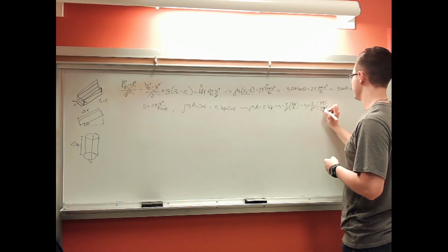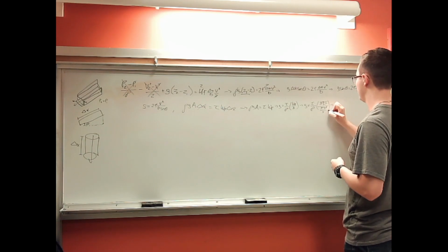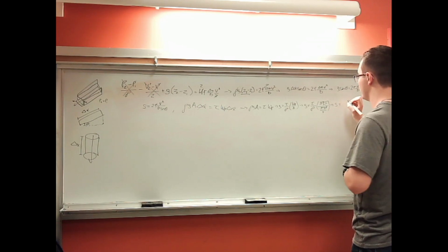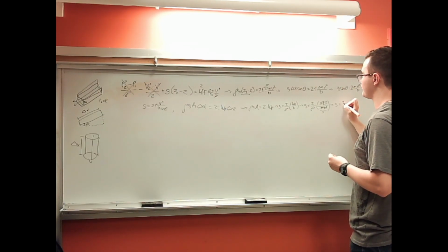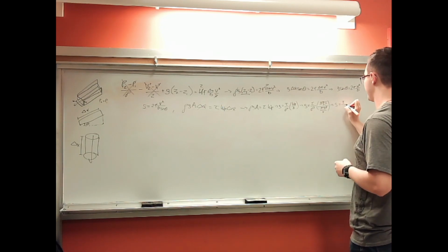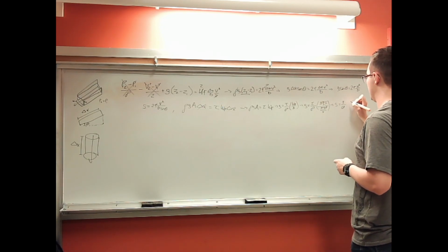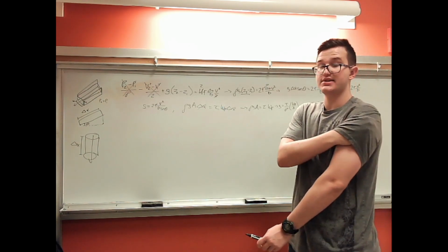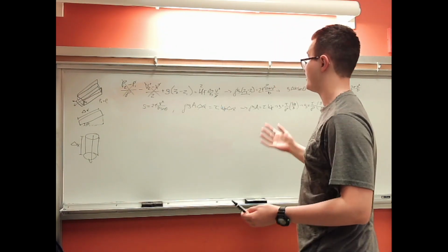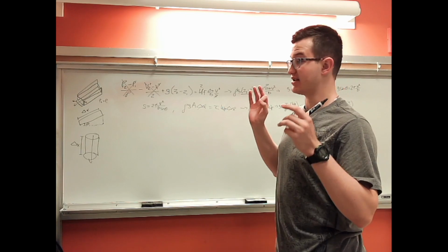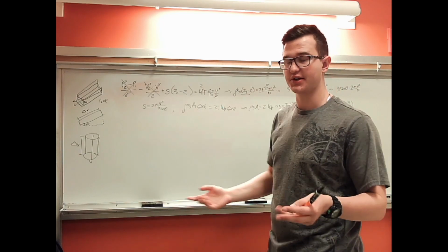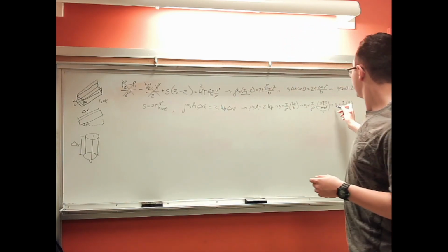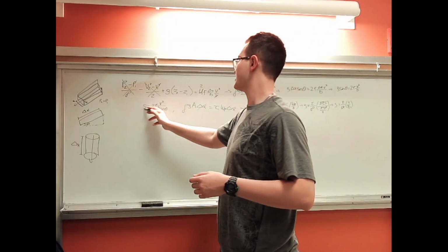These pi diameters cancel, goes to gravitational constant equals, at least in the circular approximation, the shear stress divided by the density multiplied by 4 over the diameter. And we can only do this because in the question it made sure to say that the wetted perimeter and the shear stress is the same in the rectangular channel as a circular channel or circular pipe. So we have this gravitational constant here, we have this gravitational constant here.